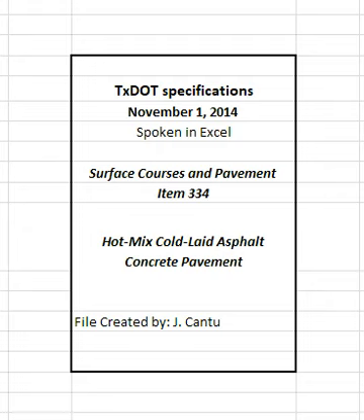2.1.1 Coarse aggregate. Coarse aggregate stockpiles must have no more than 20% material passing the number 8 sieve. Aggregates from sources listed in the department's Bituminous Rated Source Quality Catalog, BRSQC, are pre-approved for use. Use only the rated values for hot mix listed in the BRSQC. Rated values for surface treatment, ST, do not apply to coarse aggregate sources used in hot mix asphalt.